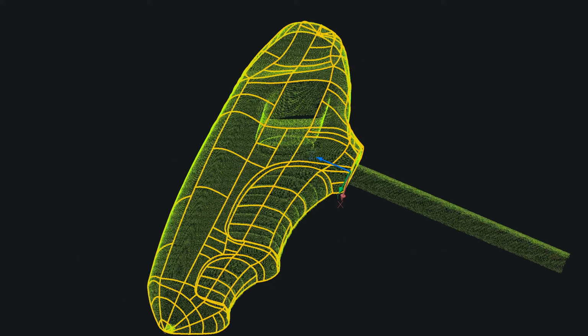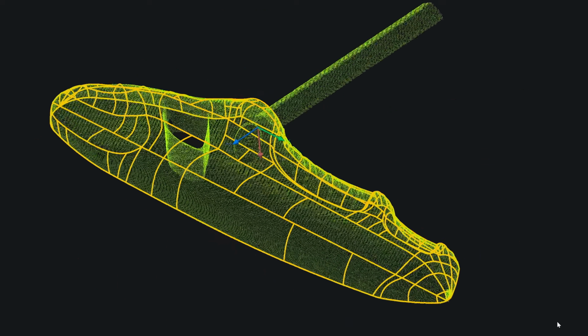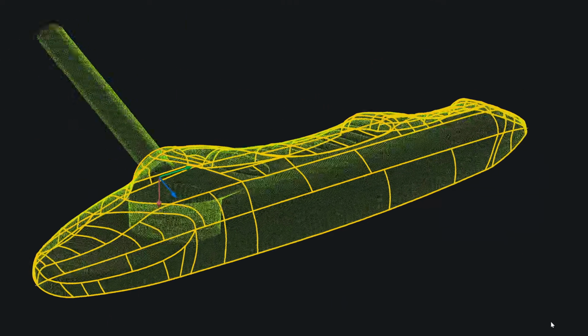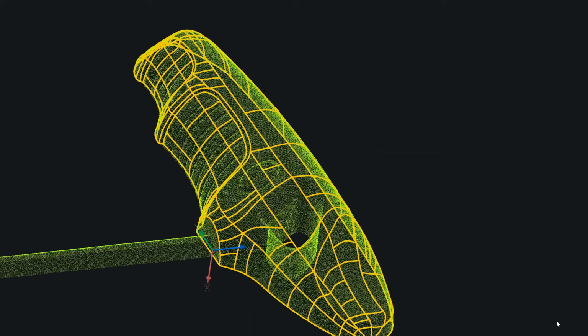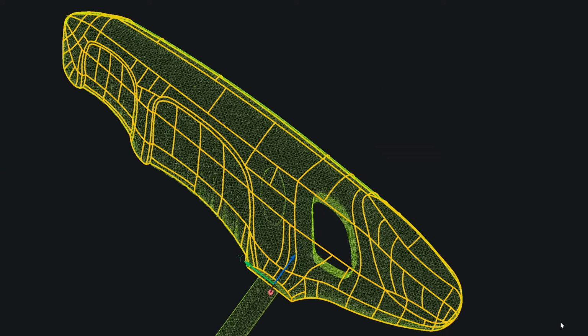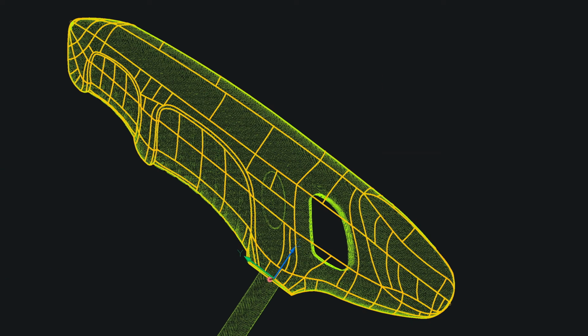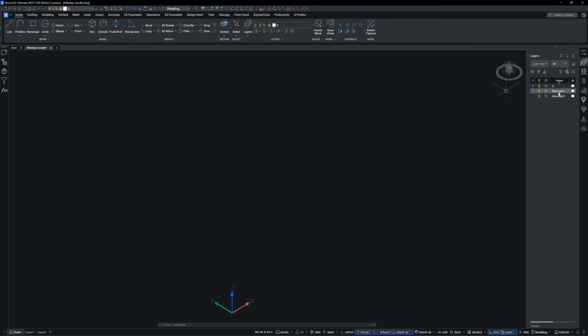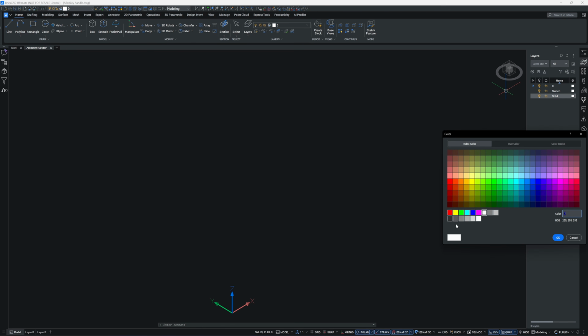If you try to build a surface boundary entirely by snapping splines directly onto the point cloud, the results usually come out less accurate. In BricsCAD, I will set up 2 layers, one for sketches and another for the solids or surface I create.